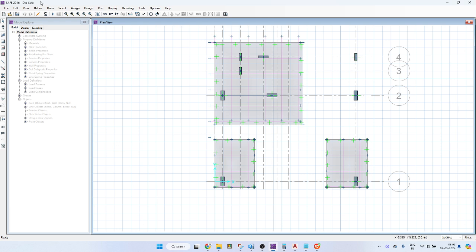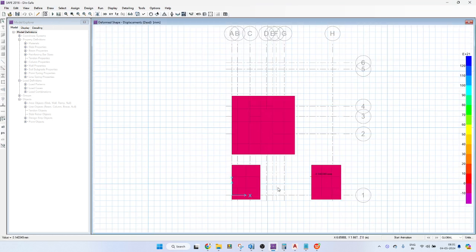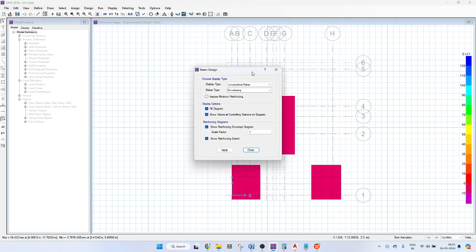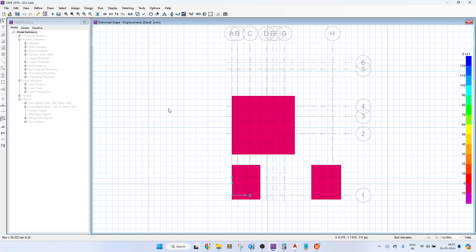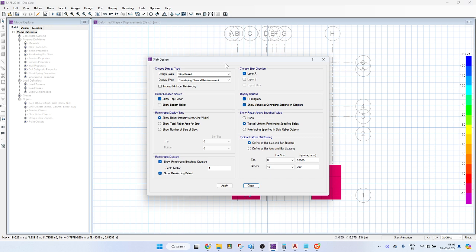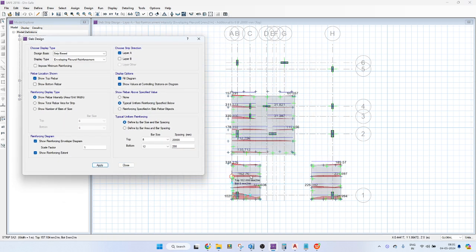So this is how you do the design, and you try to optimize things and get the best values. Each time when you get the values for each separate footing, you need to write down, because this footing specification which you are going to specify here is going to be applied for all the footings in this particular page. It is actually not required, right? You will be losing out on the data. See, for this one, if I had not written down, I don't know what I had finalized earlier. Because I've written down, I know. Okay, fine.